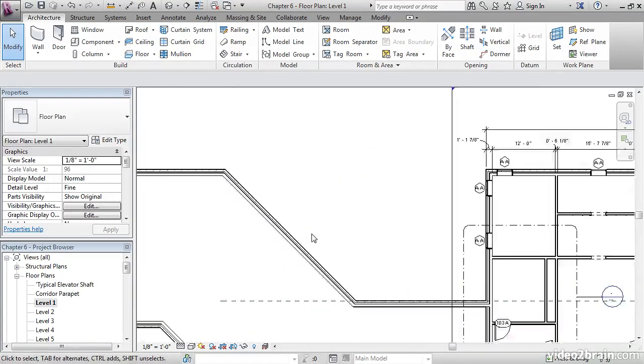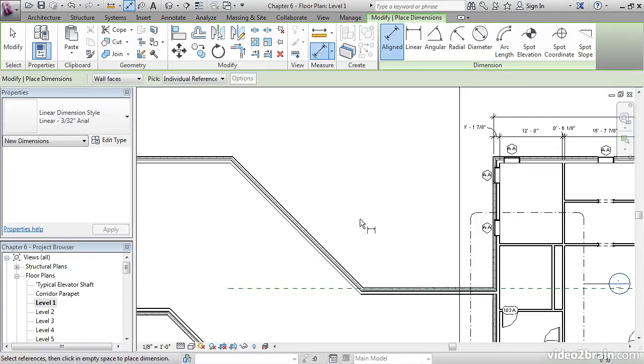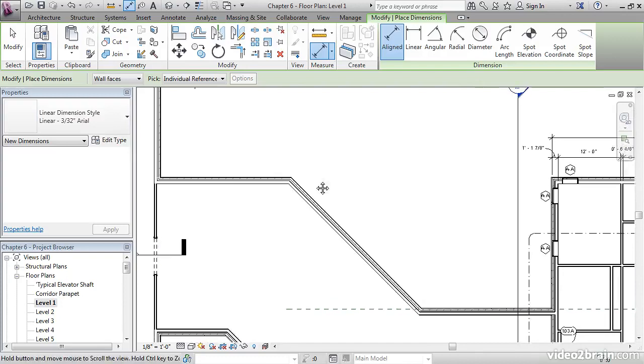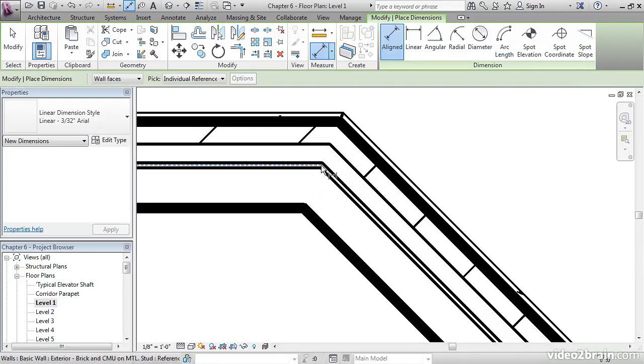Over in here. I'll fully admit Revit's not the best for angled dimensions, but it's going to work out just fine, trust me. Okay, we want a dimension to come off this wall in this direction. Not the easiest thing to do. There's a lot of tabbing involved. Here's what you have to do. Zoom into the intersection. And then hover your cursor right over this little joint. Hit the tab key several times until you get a little black dot, just like that.